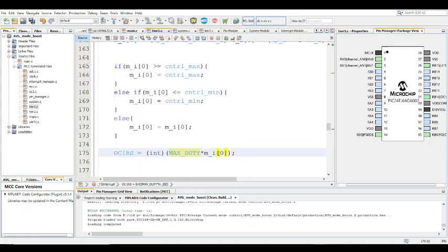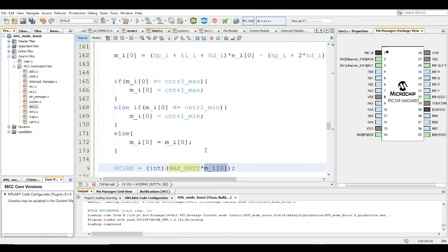And the reason why this value is limited to 1 is because when you're doing the PID control calculations mathematically, you're already assuming that the maximum output is 1. You're not assuming it's 100 or whatever your microcontroller gives.